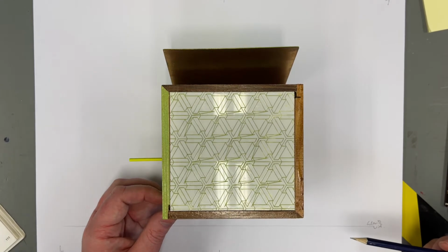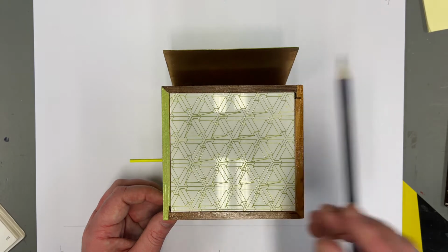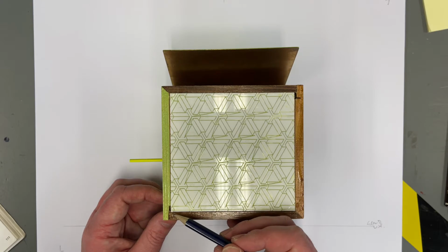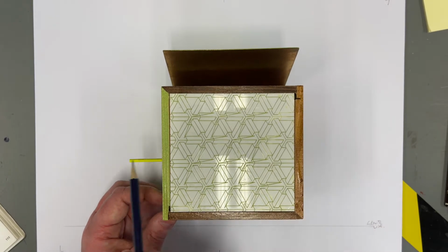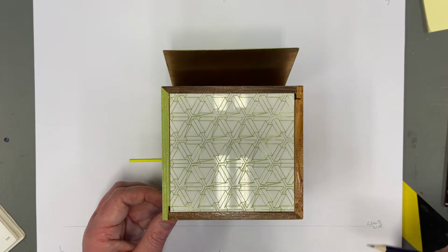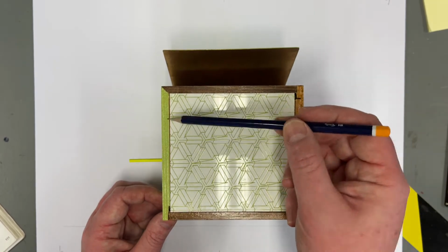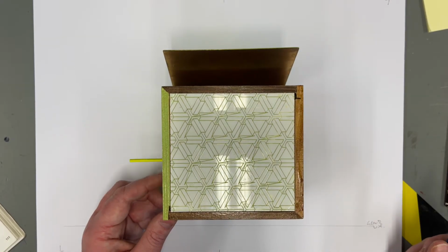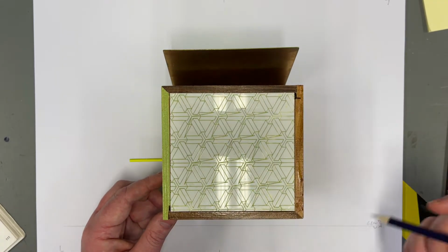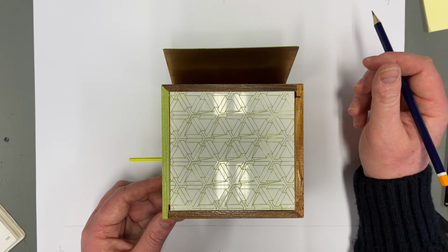Now, from this side, we can see the joints on the wood, mitre joint here, half flap joint here, half flap joint here. We can also still see the perch, and there's a couple of things hidden from us, possibly how the metal joints at the back is hidden, and obviously the entry hole is hidden. We can't see this from that side, but in saying that, because this side has the joints, it would make more sense to make that the main view, make that the elevation view. So that's perhaps where we're going to start with today.